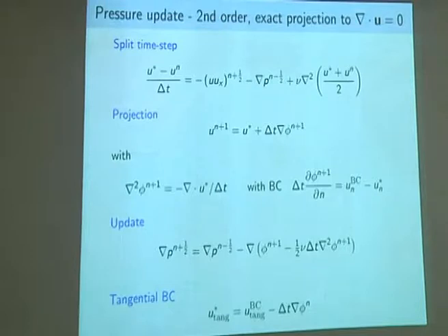Okay, so that is a second order scheme, and it's called pressure update because we keep a running estimate of the pressure, and we just update it with a small thing each time, which is much better than making a wild jump and pulling back a big amount with pressure projection. Right, I think that's it. That's time stepping on its own.